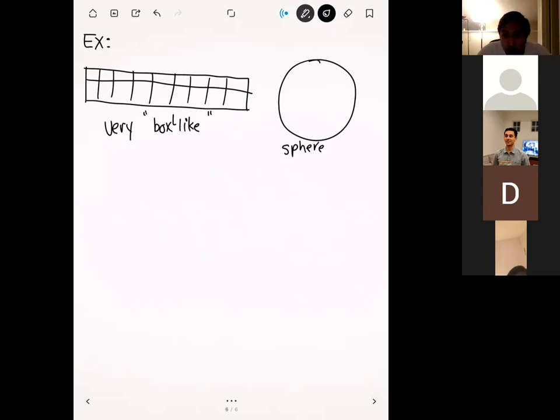Question: what about hex-dominant meshing that uses both hexahedrons and tetrahedrons, where the hexahedrons can't be formed? Yeah, I know ANSYS does have that feature. I think the setting is called hex dominant. I'm actually not sure exactly how they determine which areas are going to use hexes and which are going to use tets. But ideally, that would be the most efficient thing to do. If you can put a hex in there, put a hex because it's going to be a lot more efficient. And for the places where it can't, just fill those spaces with tets. That's the most ideal thing.